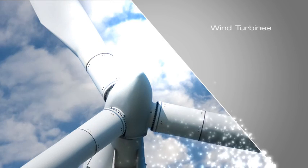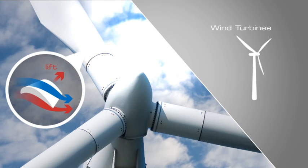Horizontal wind turbine blades are usually made of 2 or 3 airfoils like a propeller. With these types of blades, it is the lift force which makes the rotor turn. When the wind hits the airfoil, the wind gets separated into 2. It will pass over the top and the bottom side of the airfoil. Since the top distance is longer, the wind velocity will increase, therefore creating lower pressure on top of the airfoil. The lower portion will therefore have a higher pressure than the top of the airfoil, and this difference in pressure will result in lift.